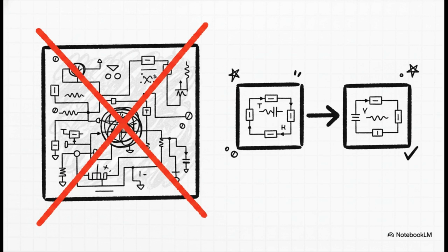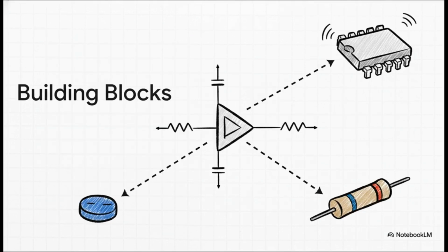And that tells the engineer something amazing. They don't have to build one giant, complicated 4th-order circuit. They can just build 2 much simpler 2nd-order circuits and string them together, one after the other. It's called cascading. And what are these simple little circuits made of? Just basic, off-the-shelf electronic parts. You've got an amplifier, which is kind of the engine, and then a few resistors and capacitors. And the exact values you need for those parts are calculated directly from those numbers in the blueprint.